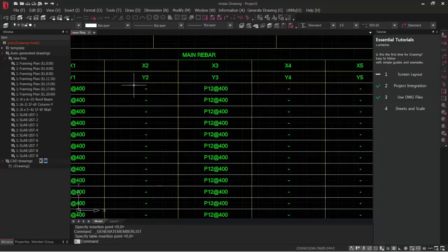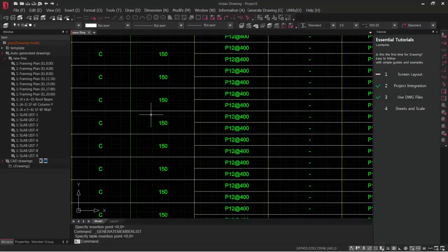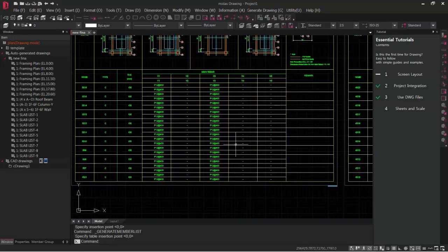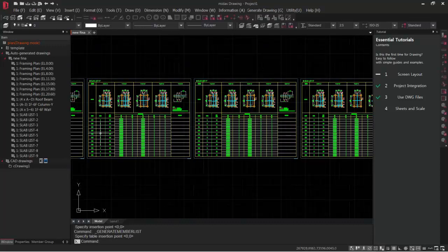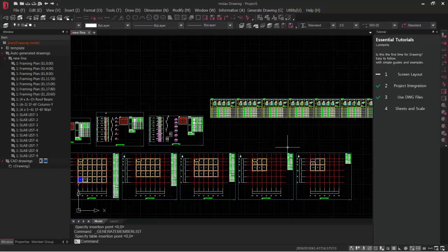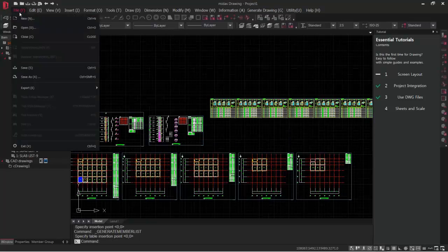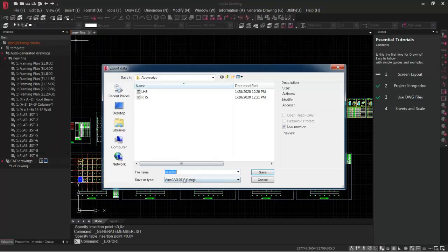This is what the program has given by default as slab reinforcements. These have been checked as per the standard, and of course after checking we are going to generate all our drawing outputs. This can be exported into a DWG file and you can use it in AutoCAD or some other CAD software solution which you are currently using.